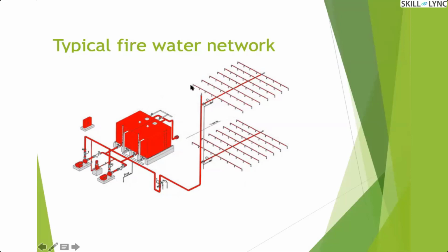But when you look at this nozzle, the distance is very less because it is the first nozzle. When the pump starts pumping, this will have a higher flow rate because it has got higher pressure at the inlet. So when it has higher inlet pressure, there is a large pressure difference across this point, so there will be a huge flow rate which is going to flow across.